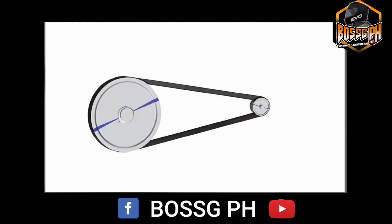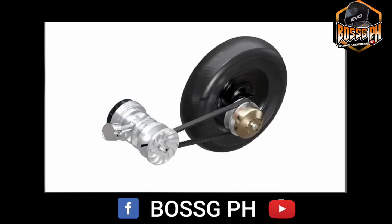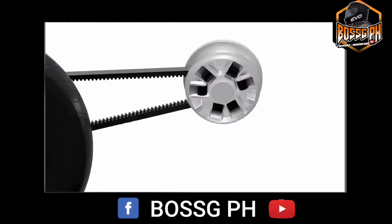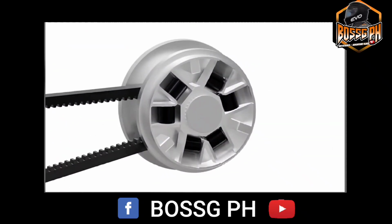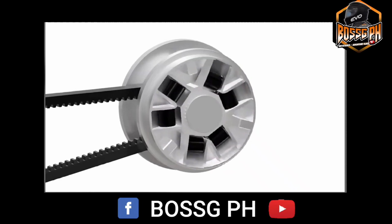To obtain high RPM, the diameter of the driver pulley decreases and that of the driven pulley increases. Let's understand how this is achieved in the actual scooter CVT. The sliding conical plate of the driver pulley has a set of rollers or sliders as shown here. When the engine is at low RPM, the rollers are held near the center of the pulley.